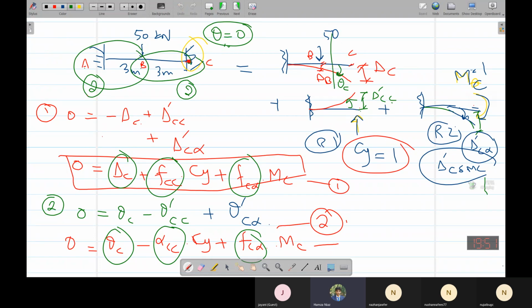For example, if we are cutting a section for B, we can take the limit as C or B. It doesn't matter, but if you take the limit as B, then you have to calculate the support reaction before. If you take C, the question will be much simpler. That's why I said first that cantilever beams are much simpler to solve.